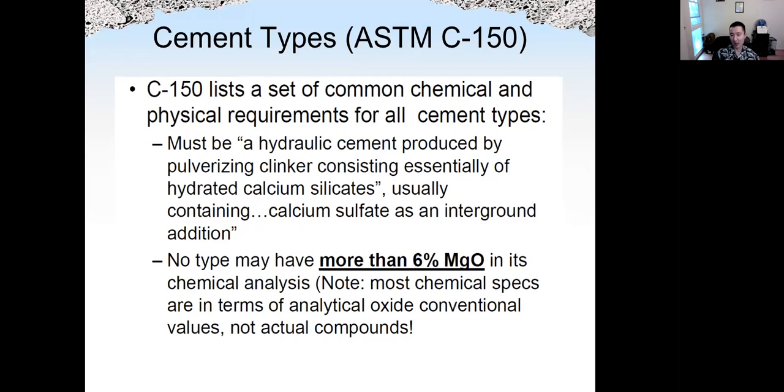We call that unsoundness. Magnesium oxide will generate magnesium hydroxide, which will cause concrete to crack. So we really limit the amount of that.